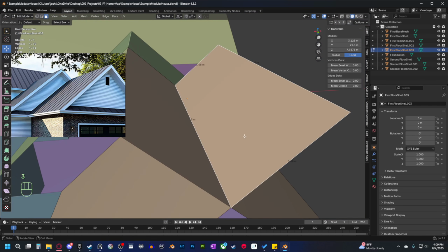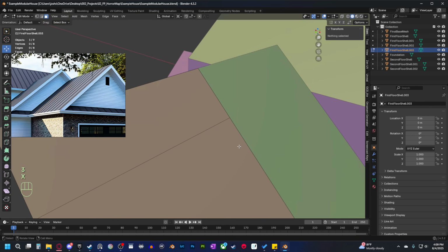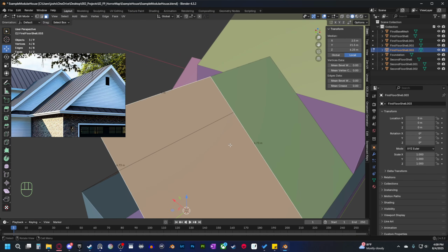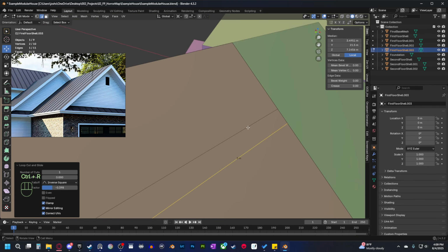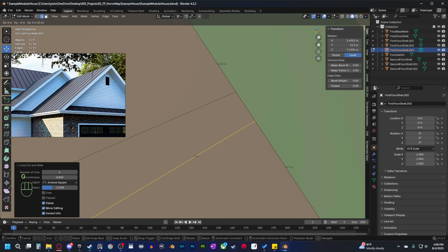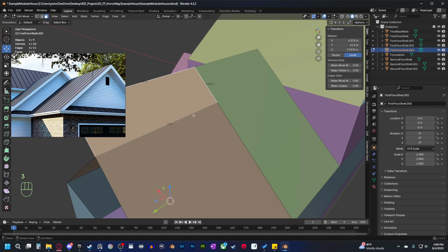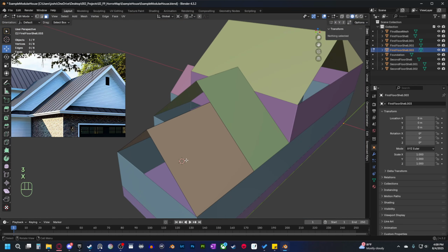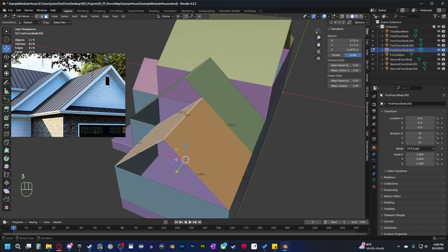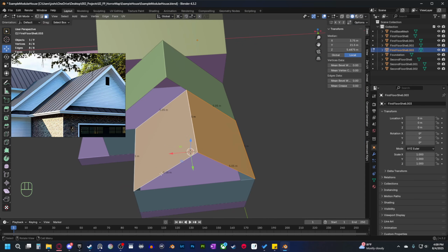And so then we can just select this and delete this face. And then we can do the same thing on this face. So this one we can just GG to slide, B to snap to there, and then move it up until we snap with that. And now I can delete that. And now we have perfect symmetry.